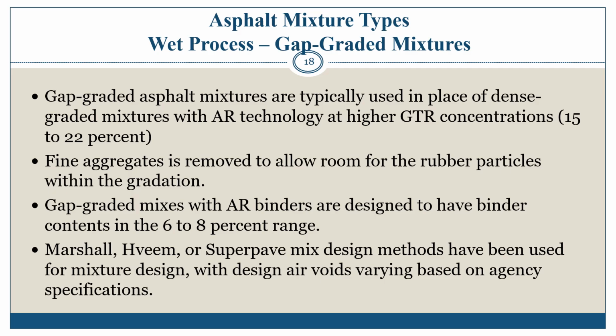Stabilizing agents are often used to aid in resistance to asphalt binder drain down. Sometimes warm mix additives may be used with GTR modified systems, allowing lower temperatures, which aids in prevention of drain down. It is important to consider the contribution binder stabilizing agents offer to mixture durability before foregoing the use of stabilizing agents.